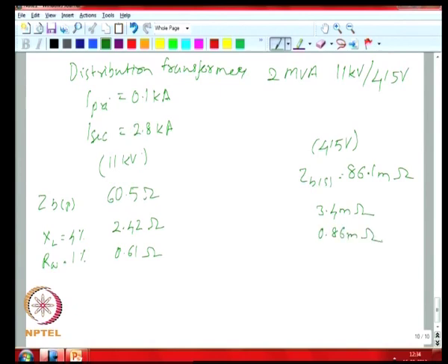Okay. So, to calculate now your fault current within the facility, you need to combine both the per unit quantities of your distribution transformer and whatever you have from the source side, which is the upstream feeder, etc. And what we will do in the next class is combine it to the voltage level of the transformer, because maybe you are more interested in designing the particular facility and look at the components that go into the facility.